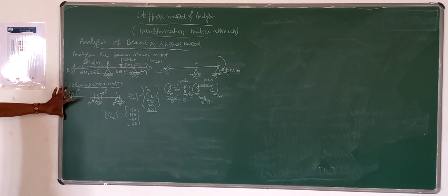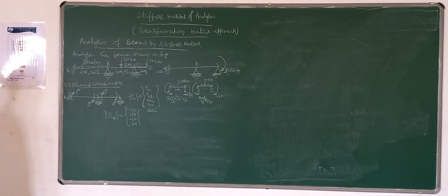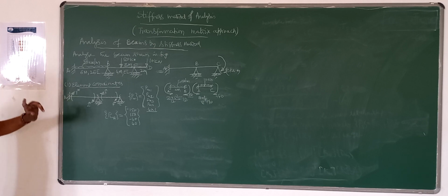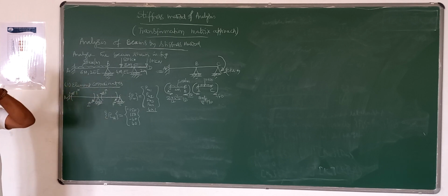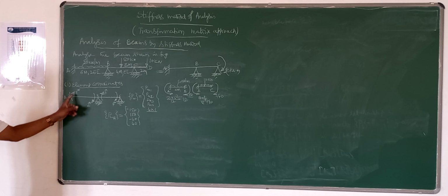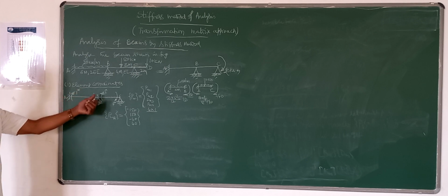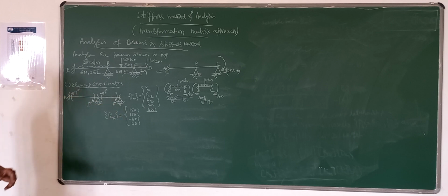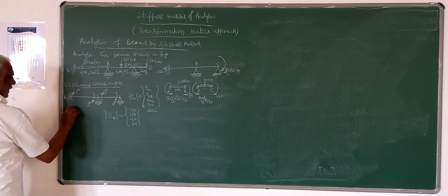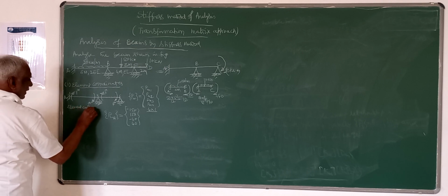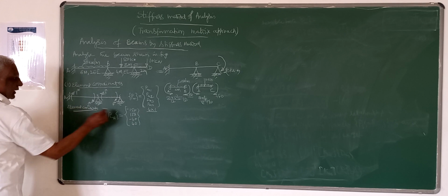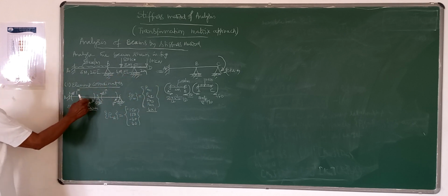So this much information you have to calculate or gather in the first step. First step, you have to identify the members and the forces which you have to determine during analysis, that is by coordinates. We call those coordinates 1, 2, 3, 4 with star. So these are the element coordinates. And you have to determine what internal forces are to be determined corresponding to these element coordinates.